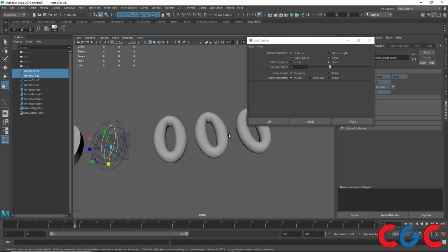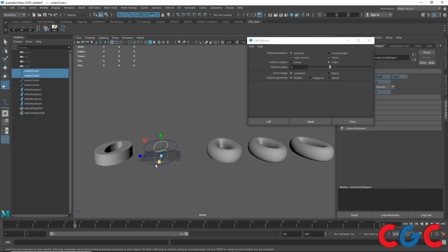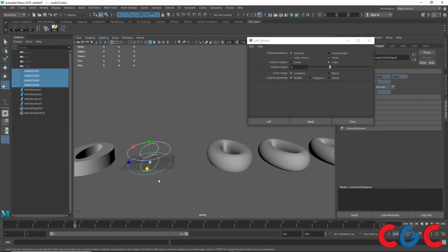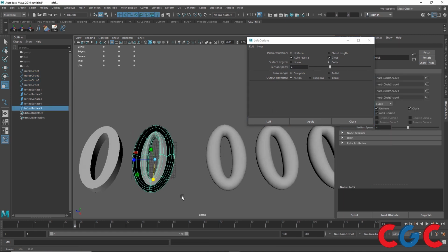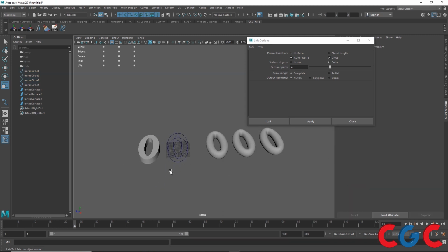So this is the advantage in using curves to model some NURBS surfaces. We will have some control till the end, and multiple objects can be controlled. And here we can see a clear difference by changing the options and creating loft surfaces. Always don't forget to select the curves in an order. If you select in a wrong order, I'll select these two and then select these two. I'll go to apply. You can see it looks different. If I want in that order, I can select and get the shape, but this is not the shape I wanted. So select in an order.